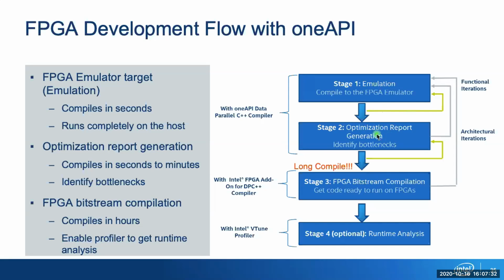After that, we can compile it to FPGAs, which implies a long compile time, hours, to get code ready to run on FPGA. So basically, here we have compilation steps, and here we have compilation plus hardware synthesis to generate the bitstream for FPGA, which is the FPGA configuration bits.